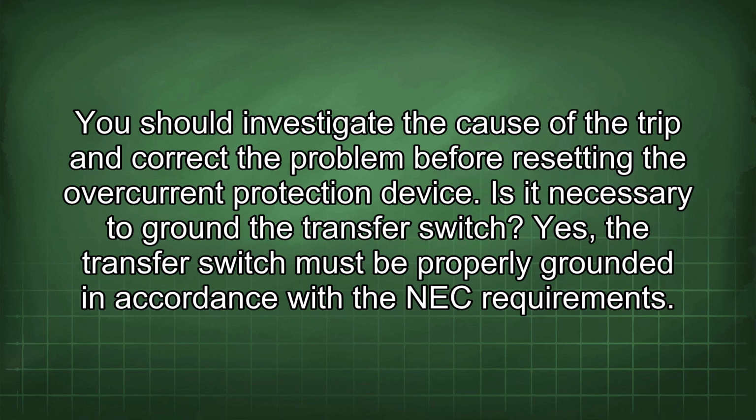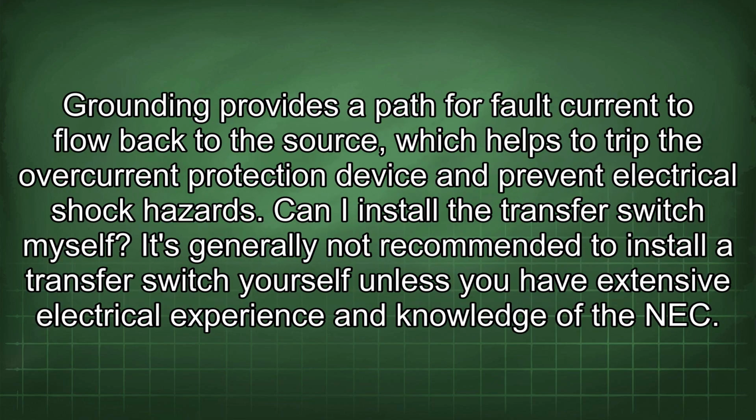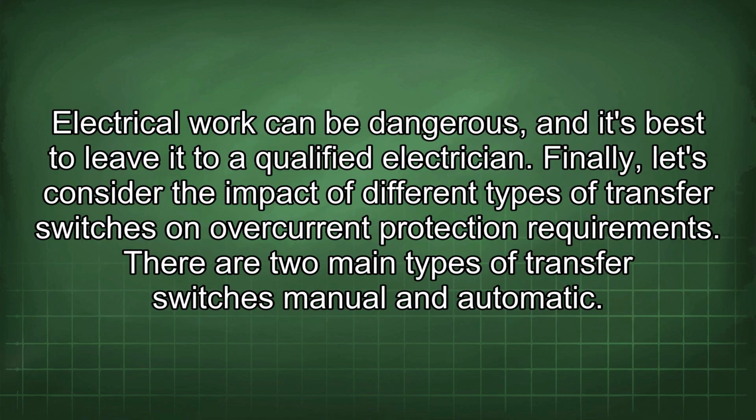Is it necessary to ground the transfer switch? Yes, the transfer switch must be properly grounded in accordance with the NEC requirements. Grounding provides a path for fault current to flow back to the source, which helps to trip the overcurrent protection device and prevent electrical shock hazards. Can I install the transfer switch myself? It's generally not recommended to install a transfer switch yourself unless you have extensive electrical experience and knowledge of the NEC. Electrical work can be dangerous, and it's best to leave it to a qualified electrician.